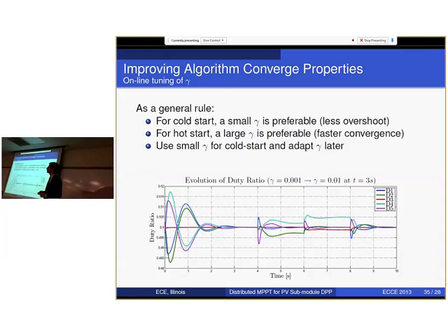Gamma affects the update overshoot, but also the fact that you're estimating the derivative, right? Mm-hmm. And you have different information now, like what we saw before, you're not getting direct information from that communication link that failed, right? So now your estimate of the derivative is large, which is amplified by your gamma. So I think that's the reason it happens with communication failure, right? Yes.